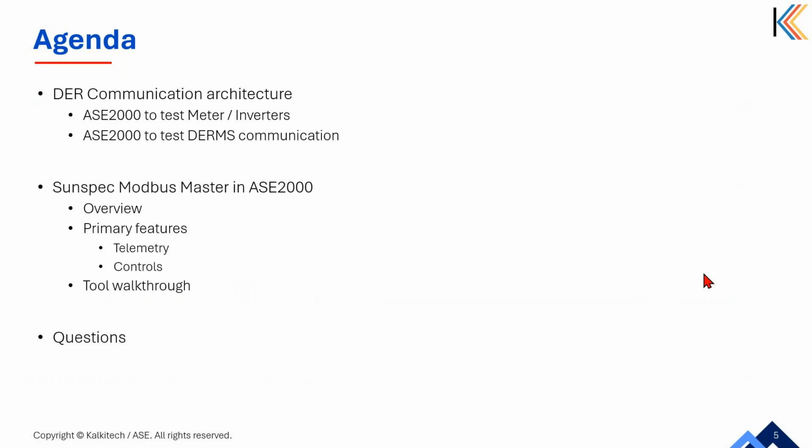Another capability of DER is the option to send schedules or controls. In SCADA protocols, generally we send latch on, latch off kind of commands, right? And pulse commands in general. But here, most of the commands are in the form of schedules, and that requires a different set of capabilities. Because of all these reasons, IEEE 2030.5 is considered a better protocol for site to DERMS communication.